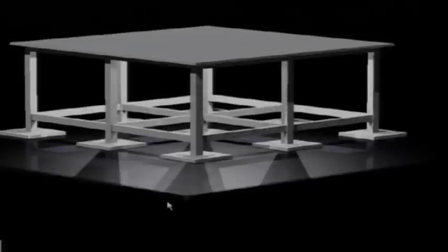We have started from the bottom, but when we design, we do it the other way, we start from the top. So, slab, then beam, then column, then tie, then footing. This is how the design will proceed. Even if you have a staircase, it has to be designed first. This is just one schematic.